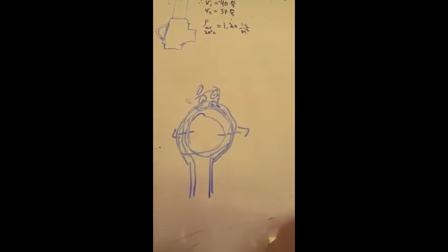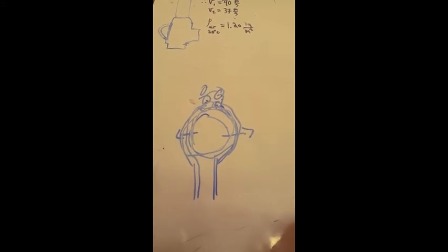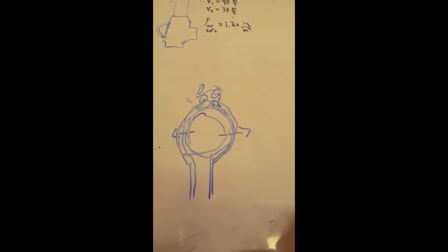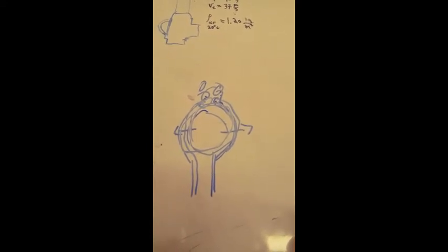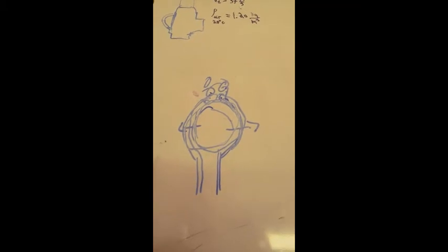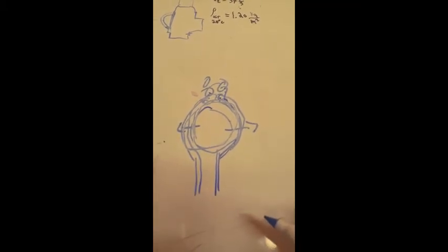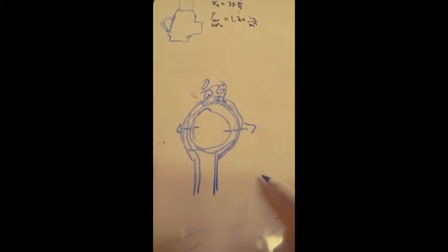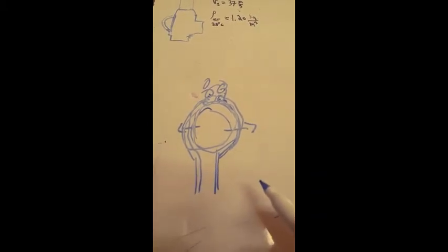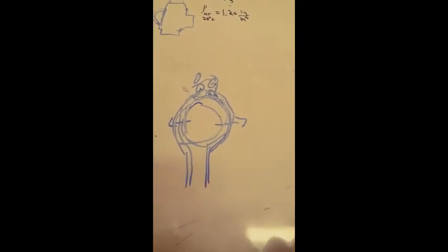When there's a curved surface underneath the jet stream, the atmospheric pressure zone between the stream and the surface begins to diminish, and the jet stream is pushed downwards by the atmospheric pressure above the stream. This happens all along the curve. So when the air hits the ball, the stream hugs the surface of the ball. When the ball reaches the very edge of the stream, there's a low pressure zone on one side of it and a high pressure zone on the other. So the high pressure zone would, just as for the jet stream, push the ball back into the jet stream. And this is what we see is actually happening.